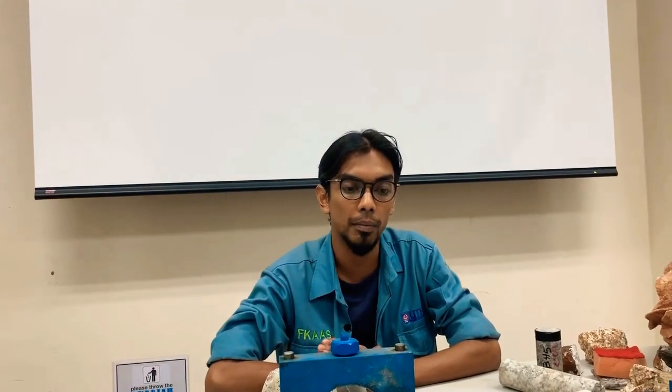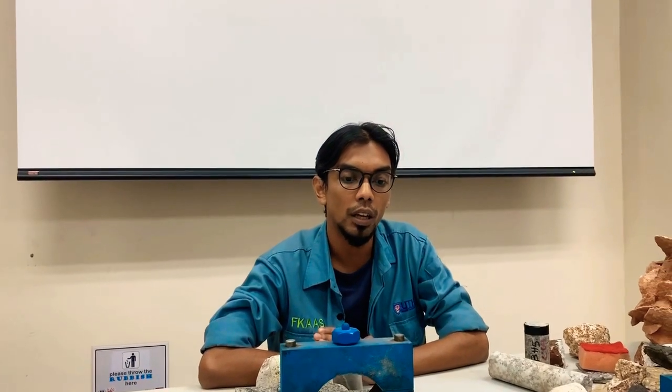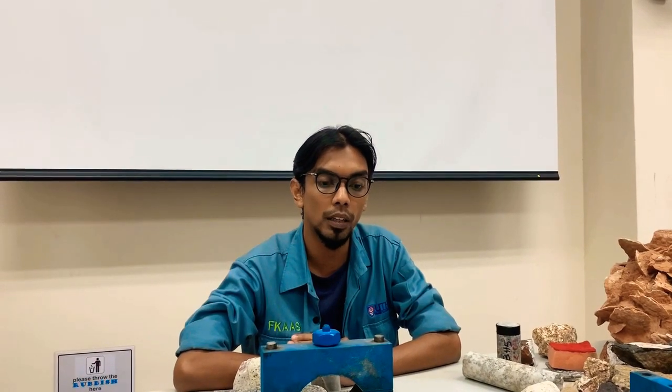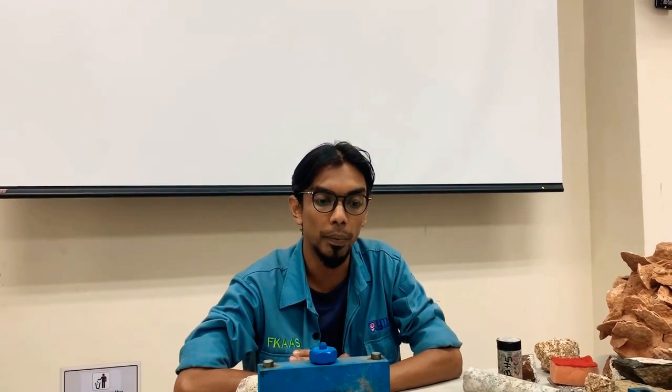From the findings and observations, the most suitable method is in situ stabilization using in situ bucket mixing or excavation mixing, because the method and procedure implementation and the equipment involved are not too complicated, and do not involve a complex system or high technology equipment. This method is the simplest form of mixing and can be used to mechanically mix reagent and other additive material with soil. This technique offers a cost-effective and schedule-efficient solution.